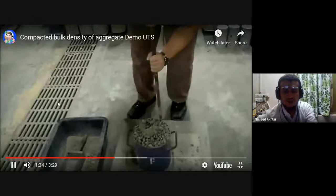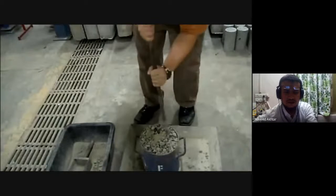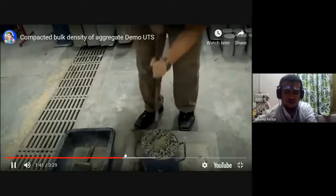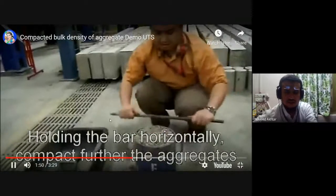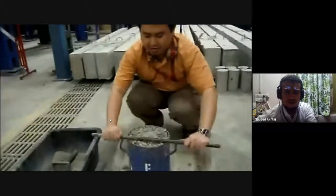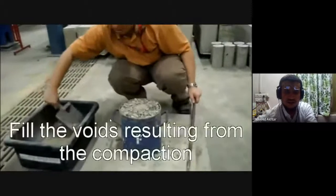So each layer is compacted for 25 blows and the container is filled in three layers. Then it will be leveled and the weight of the container is taken.